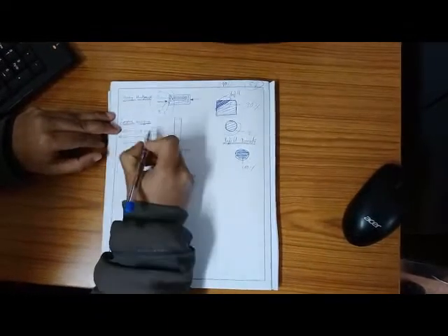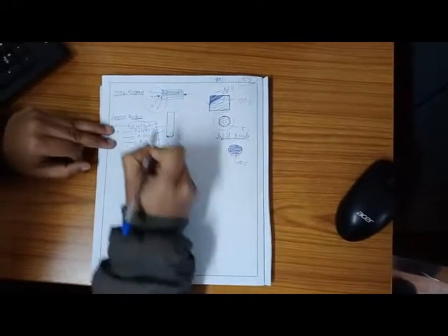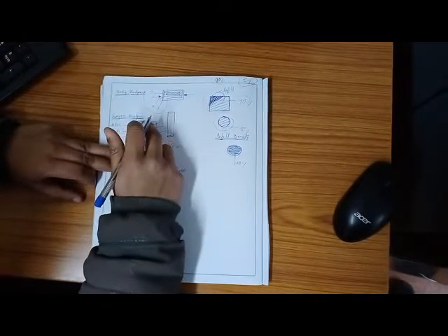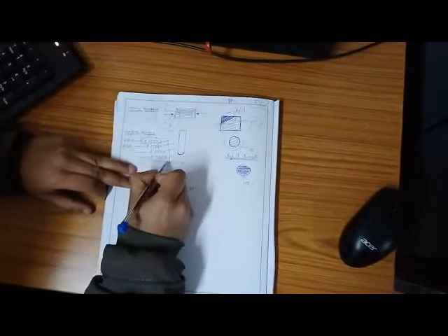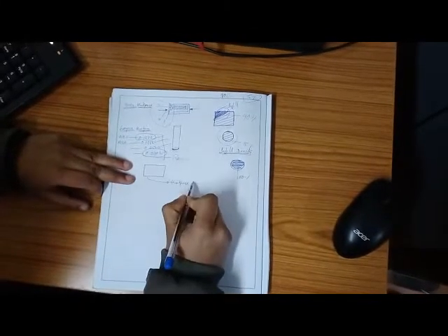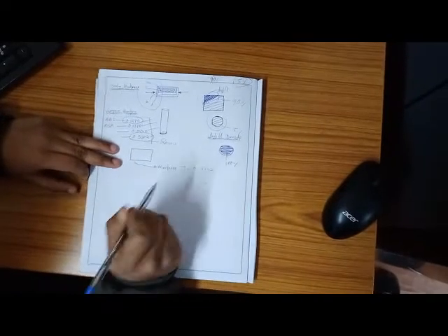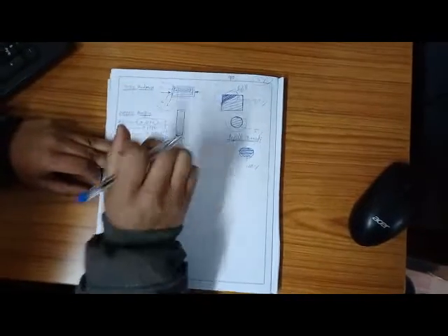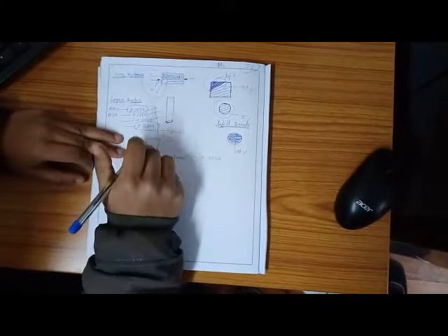If we keep it lower, suppose we select 0.127, that means our thickness will be 0.127 mm, and by selecting this we are improving the quality of the printed parts. If we select this resolution, 0.3302 mm, that means the thickness T here will be 0.3302. Our print quality will decrease because we are increasing the thickness. If you keep it lower, it will create the model very minutely. Fine, so this is the thickness we have here.